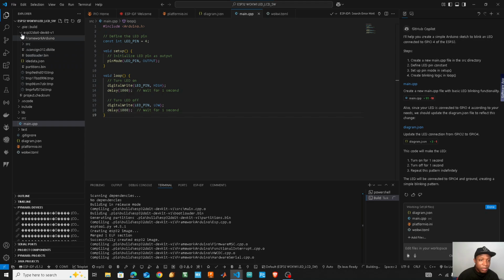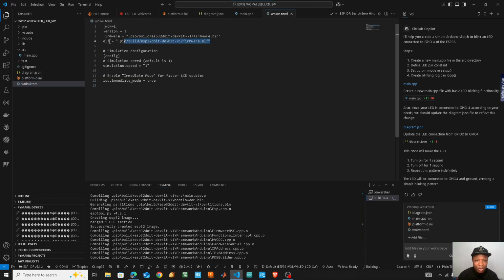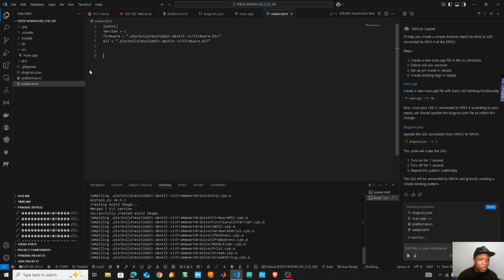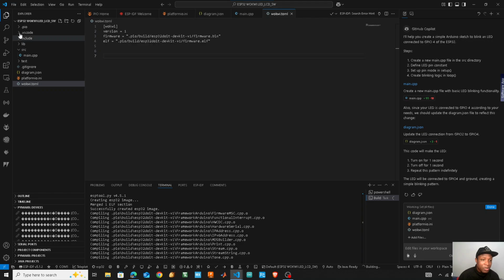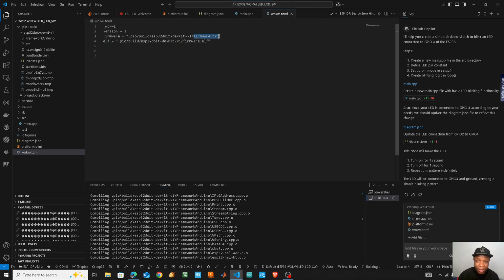So as we were saying, if we go to this Wokwi.toml file, these are the 2 most important lines of code that we first need right now. These ones, yeah, we'll get them with time, but I can even get rid of them just for us to stay in line as we go. So in here, you have the name of the board, whatever board that you chose, its name should be here. And as you can see, as it's building, we're having some temporary files that are being created. And at the end of the build, we'll have these 2 files. Okay, the firmware file and then the linker file. Both of them should be here.